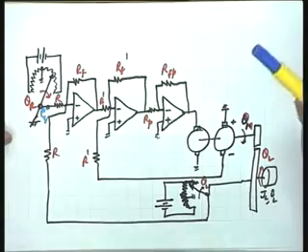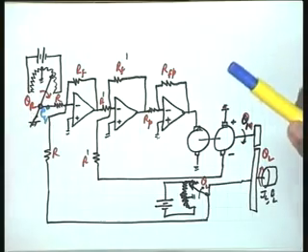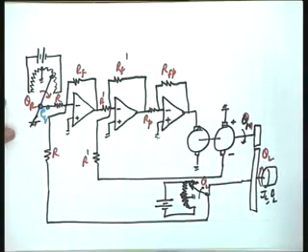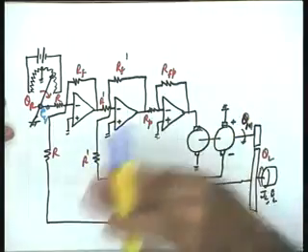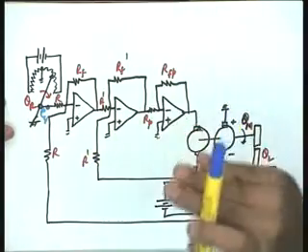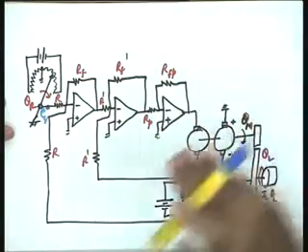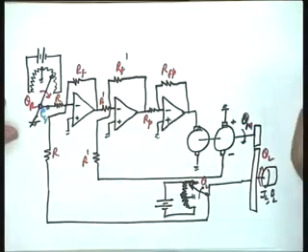You will please note that a potentiometer again leads to nonlinear problems, because it has a finite resolution. A wire wound potentiometer, for example, will only change step by step and will not give you a continuous movement.